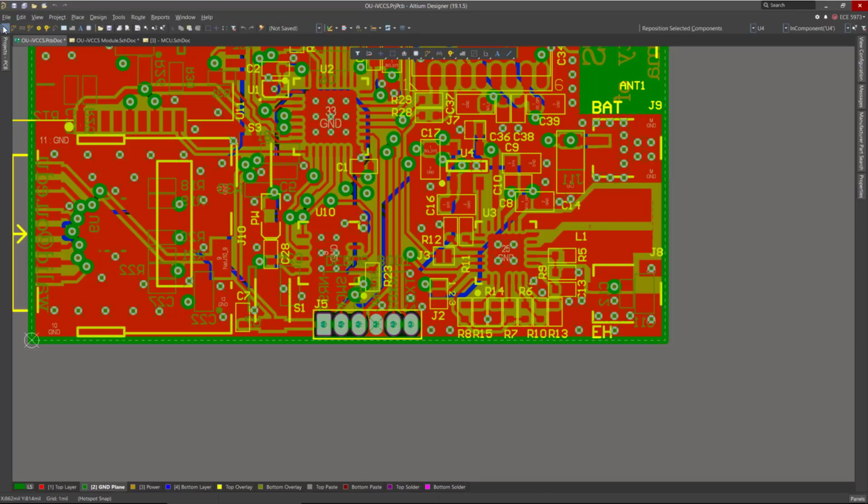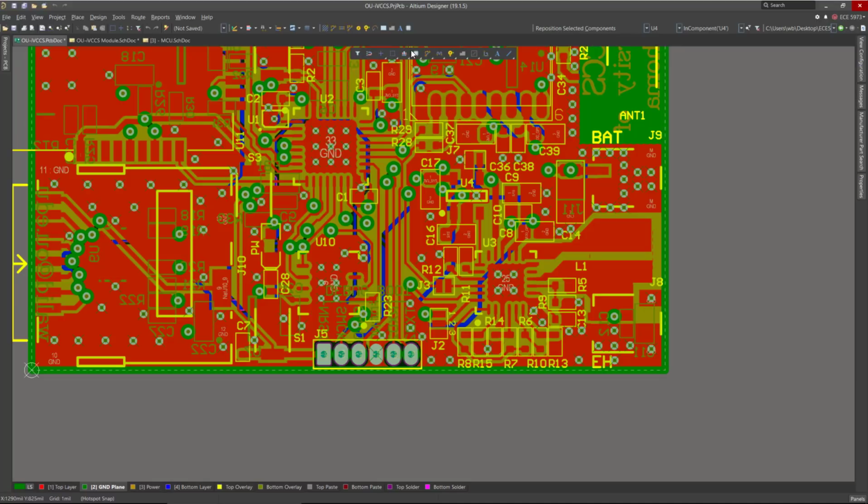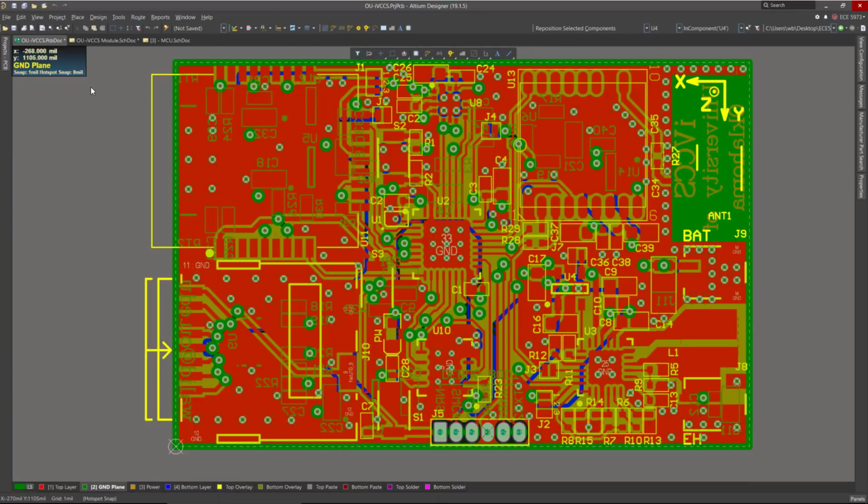Wiring. And the wiring in the schematic is different compared to the wiring in the layout. In the schematic, you have nets. In the layout, you have traces. So don't mix them. Navigation, same thing. I also keep these active all the time. So again, in the document editor, we talked about that. You can arrange the documents or close and open any of them.